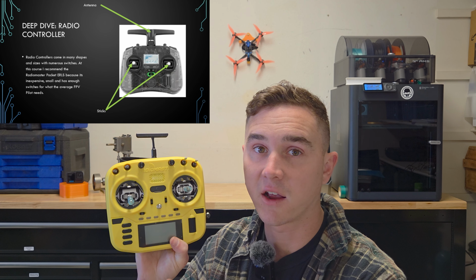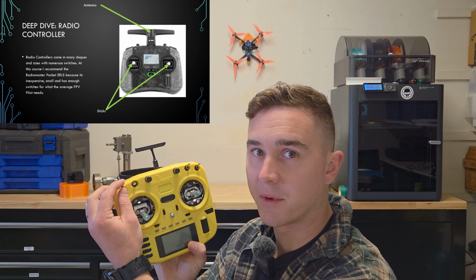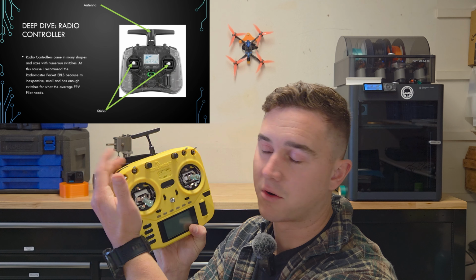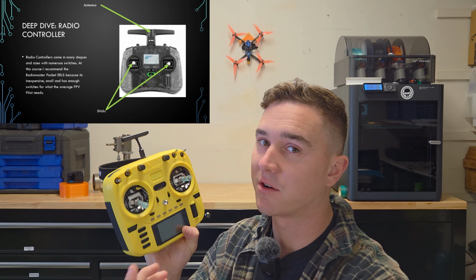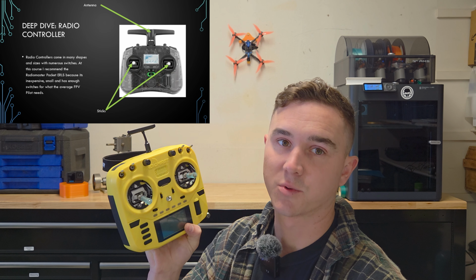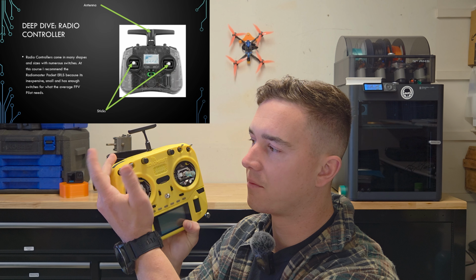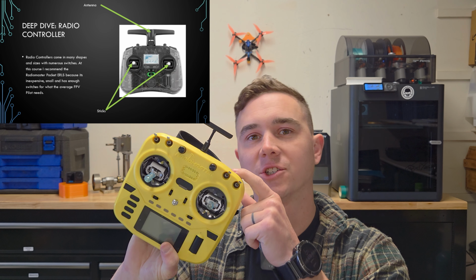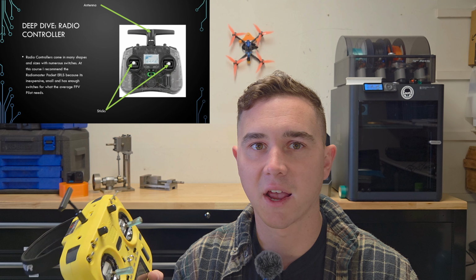For FPV, I don't use a lot of switches. I basically use an arm and disarm. I use a flight mode switch. So we'll say at the top I have acro mode always, because standardly you want to start with your switches away from you. At the top I'll have acro, middle horizon, bottom angle. Then I also have flip over after crash on a momentary switch. That's just my preferences. But in total, I only use a handful of switches.